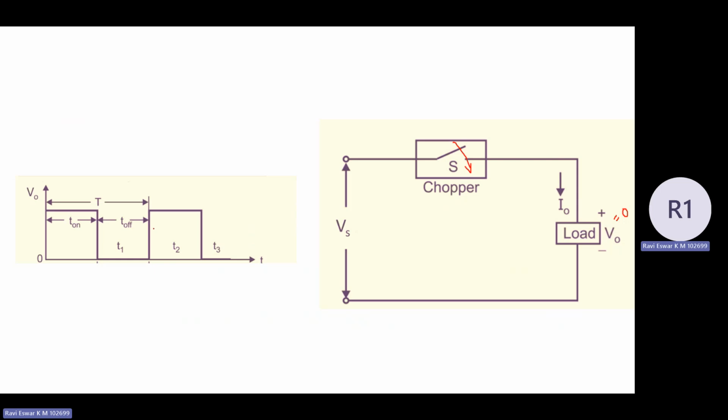When the switch is fully off, the current is ideally equal to 0, but the voltage is present across the switch. The resultant power consumed by this regulating device is 0. That's why we employ these switching semiconductors in power conversion, and we are going to observe efficient power conversion.